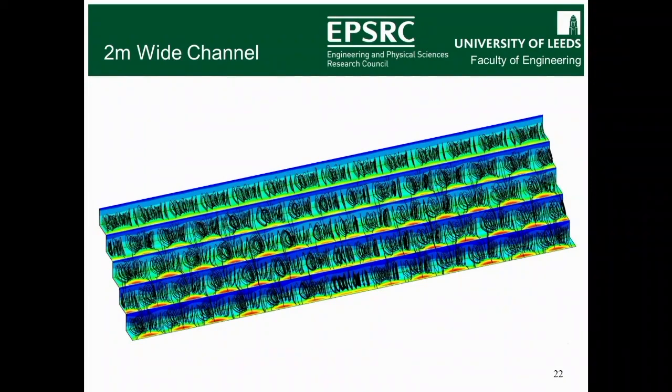We have superimposed some smaller steps into the spillway to double the ratio of step height to channel width, and you do see this pattern of 4 vortices across the channel width, but it'd be interesting to see what would happen if we could extend the experiment out a bit further.